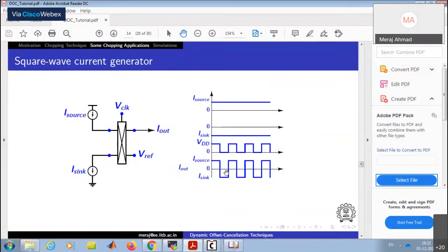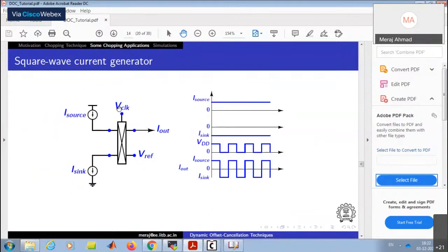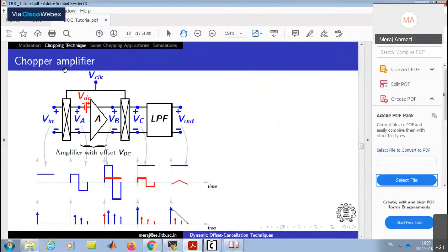Here also we get a square wave. If we have a voltage input and use a modulator, we get a square wave output. Now, if we have a current excitation as a square wave, and we pass this current through a resistor, the output will be similar to what we have in voltage mode. What she covered was resistance measurement for bioimpedance applications, where we need current excitation. The principle is exactly the same. This chopper is removed, and we have a square wave current which flows through the resistor.